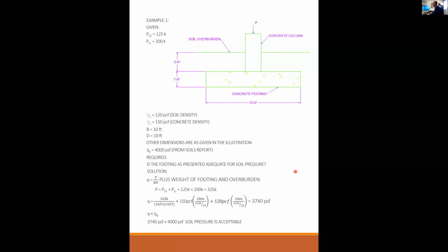Gosh, this is going back a ways, but if I remember from that foundations class, it is either that the footing itself is going to sink too far. There's a limit on how far you want to let this thing settle. All footings sink, right? You put a mass on top of soil, even if it's 2 pounds, it's going to sink into the soil a little bit. So all foundations are designed to settle some, but they shouldn't settle too much. Okay, so that's one criteria.